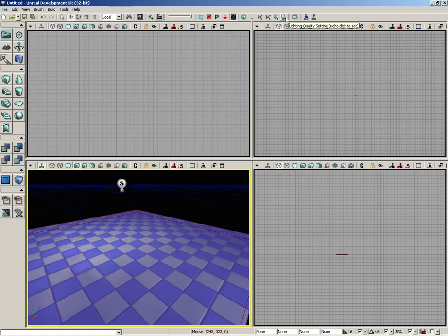Next, we can choose our lighting quality settings. Now, if you left-click on this, you're cycling through your different levels, with the little I being preview quality, then there's a little letter M for medium, then high, then production. If you right-click on this, you can choose in a drop-down style which one you want to use. I'd recommend staying on preview for as long as you can.